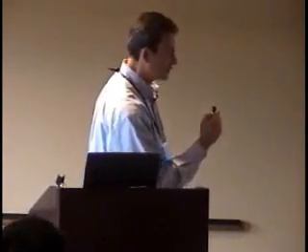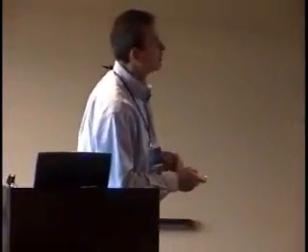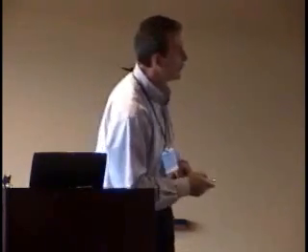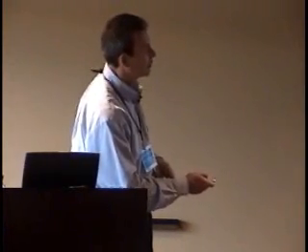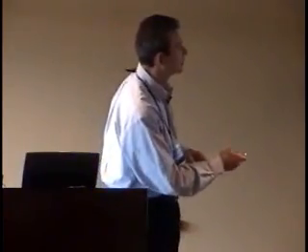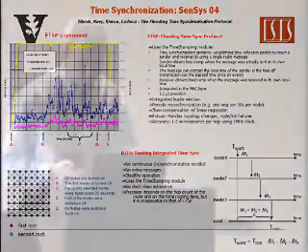These graphs show experimental results for a 5 by 6 randomized grid. My laser doesn't work. The ground truth goes around 5 centimeters, and using this algorithm, the mean error for the localization was around 7 centimeters. And around 85% of all the nodes were within 1 lambda, where lambda is the wavelength of the carrier signal. Of course, in order to do that, the nodes should be synchronized.